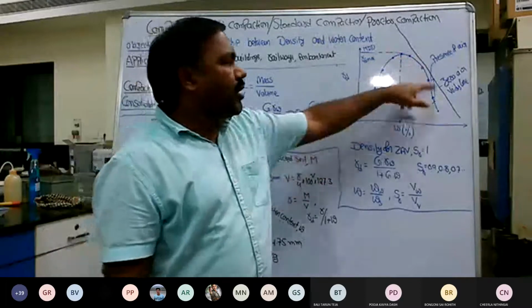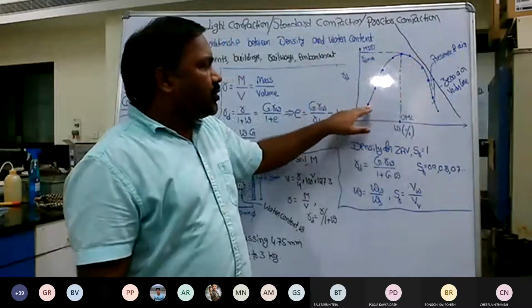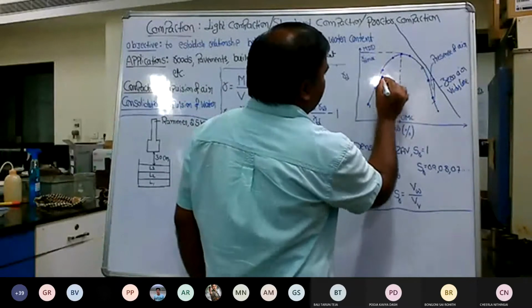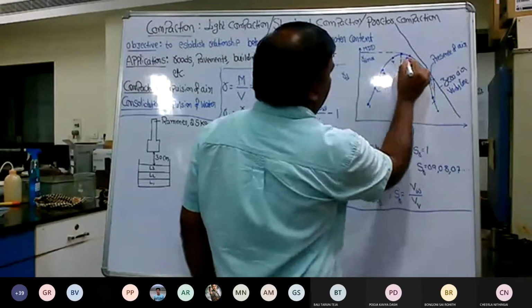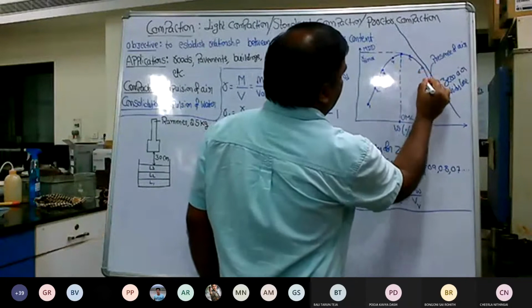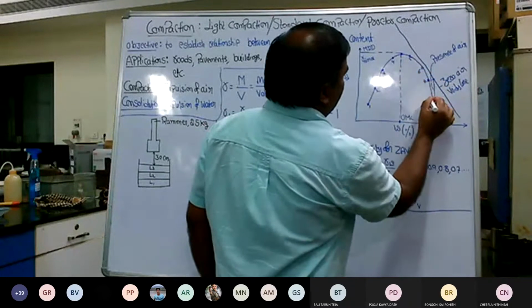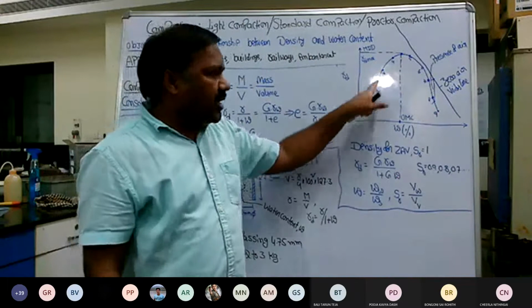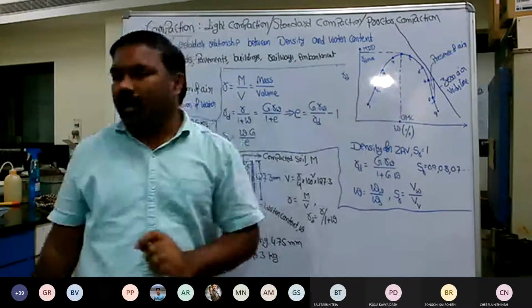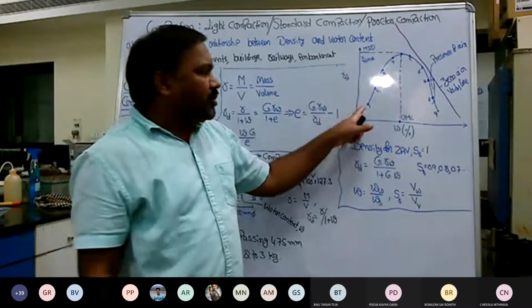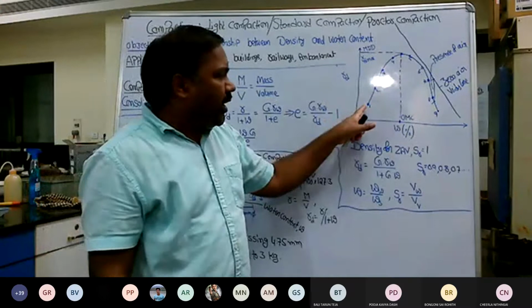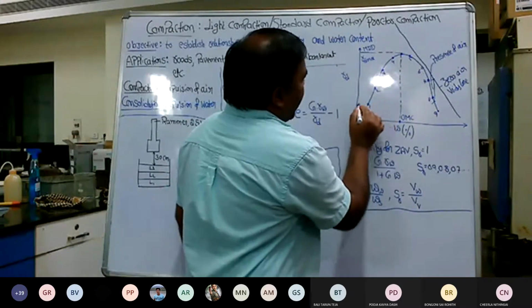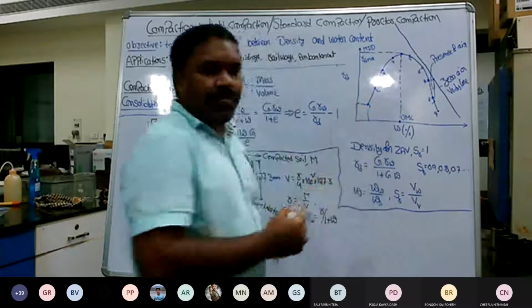So it is an upward curve. Each point represents some amount of moisture content and density. Here I have shown some points. The compaction test was done on approximately 9 samples. Suppose you look at sample 1: some amount of moisture was added initially and we achieved some density.